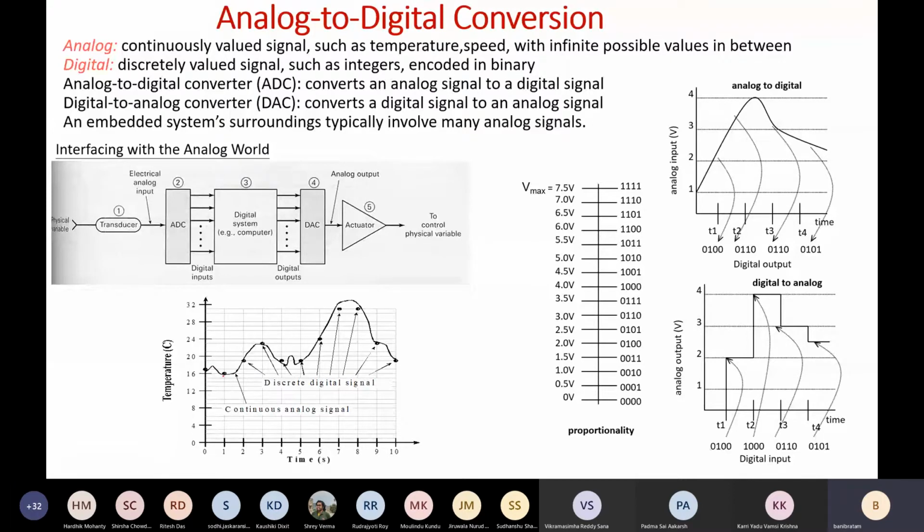Now if we want to convert it into digital, what we will do is discretize it. Suppose along this axis we are discretizing it in these intervals. So typically this is the signal, and we discretize it vertically, right? Discretize means at some regular interval, like at 1 second interval or 1.5 second interval and so on, right? And then after discretizing, we will get these discrete values. Here only a couple of discrete values we will be getting. Here you can see the dots.